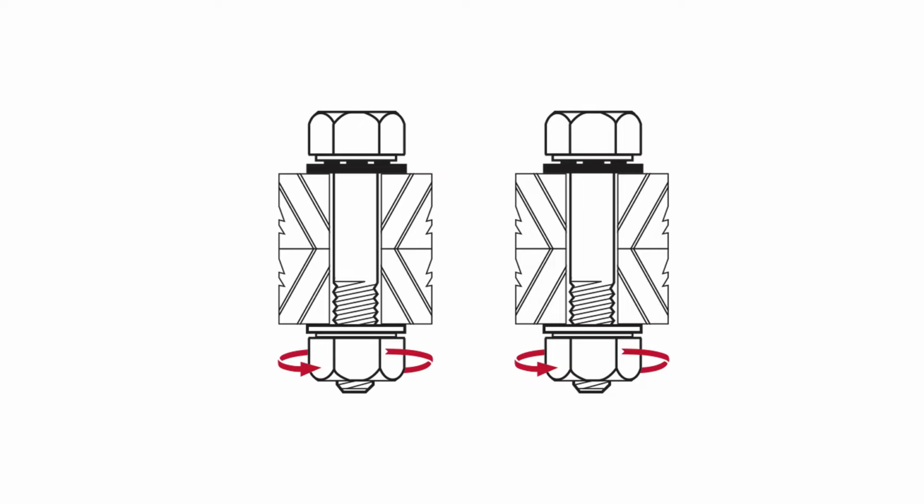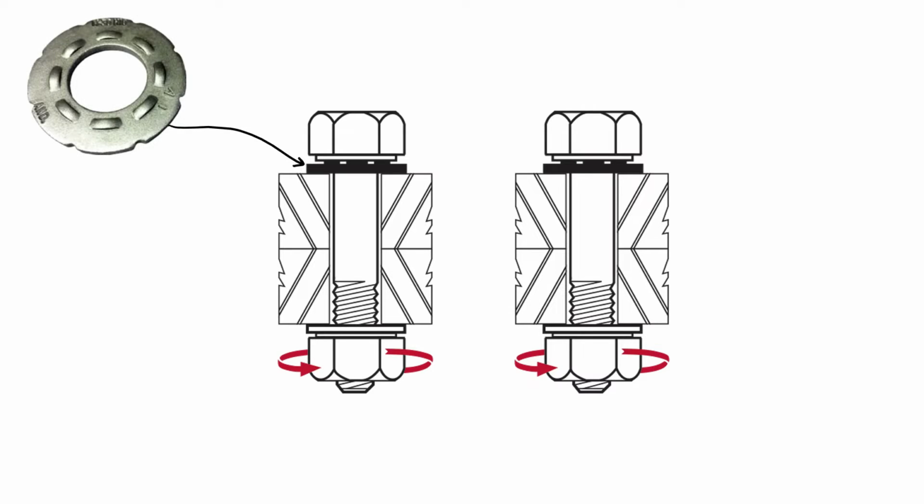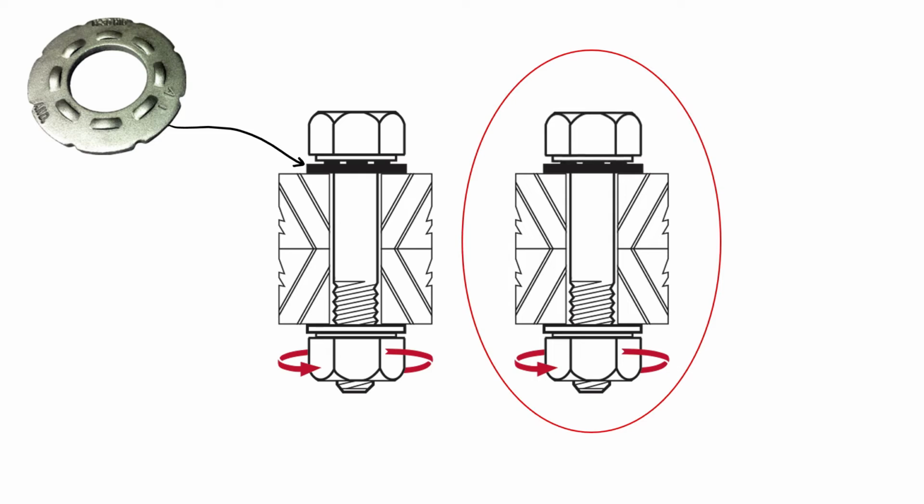The most common of these devices is a washer with protrusions on its surface. When the bolt is tightened, the protrusions are compressed in proportion to the tension in the bolt. A prescribed amount of deformation can be established for any bolt, and when that amount has been achieved, the bolt will have the proper tension.